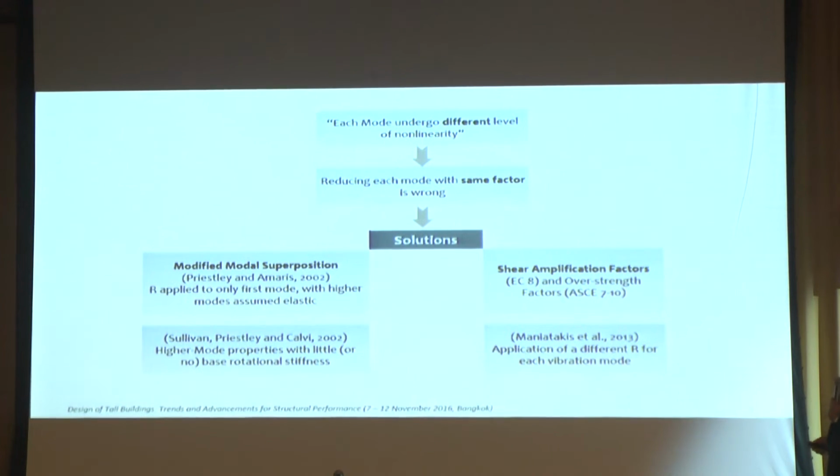The most famous solution for this problem is modified modal superposition. Basically, Priestley and his team have proposed this. He simply recommended that R should only be applied to the first mode, because mostly the inelasticity affects the first mode. So only that mode deserves the reduction, and higher modes don't deserve that reduction by R.